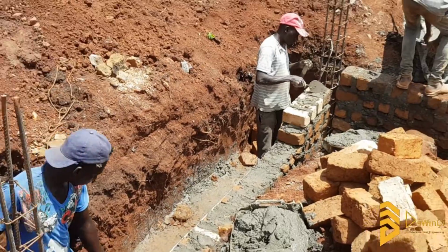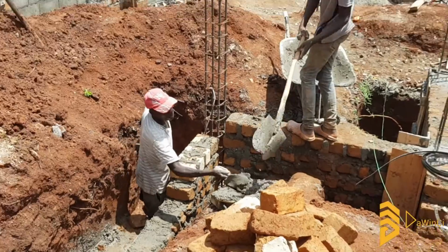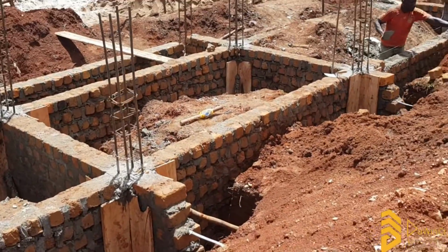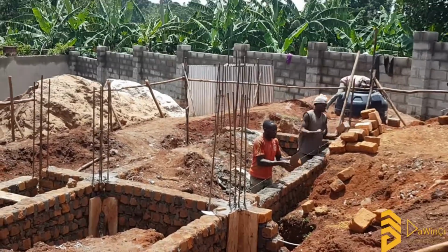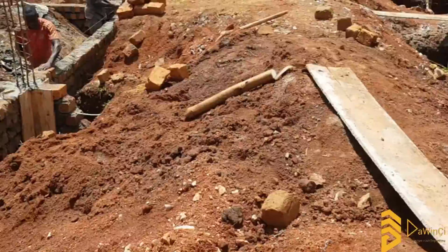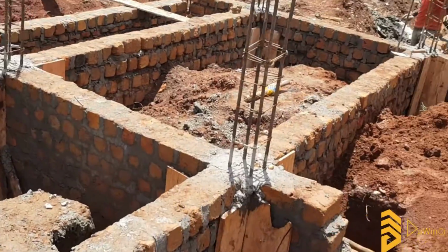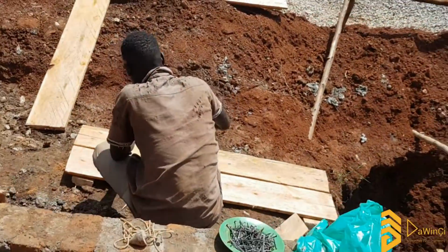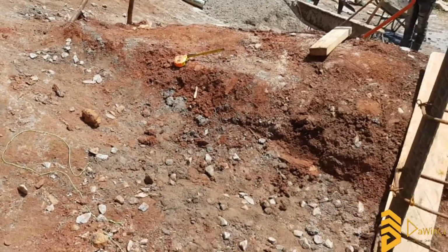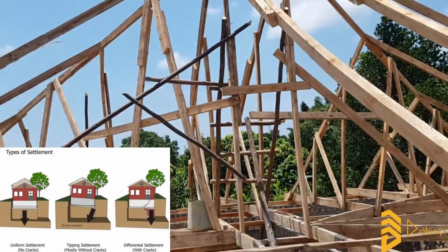So there are people who actually mess up when it comes to construction and they don't even include hoop iron in their substructure walls, even actually in the superstructure walls. But the function of hoop iron is actually to take the tensile forces in the brickwork. You see, when you lay down the bricks, usually in the plinth wall, that is in the foundation wall, you realize that after every few courses of brickwork, you have to put hoop iron. So this hoop iron actually helps in reinforcing the brickwork so that it can take up the tensile forces.